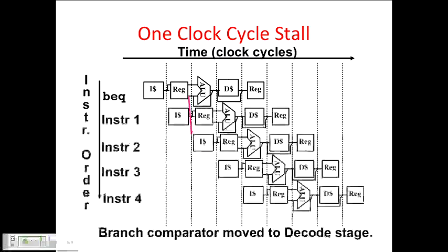So notice this is a case where the instruction set design has been influenced by circuit and pipelining details, right? In fact, the whole RISC instruction set is designed around allowing you to build efficient pipelines. It's not about having as few instructions as possible. It's about building machines that are fast, that are good at being pipelined. That's where the RISC ideas really come from. So this is another example of thinking about the implementation in designing the instruction set. So they could cut the branch penalty down to 1 cycle this way.